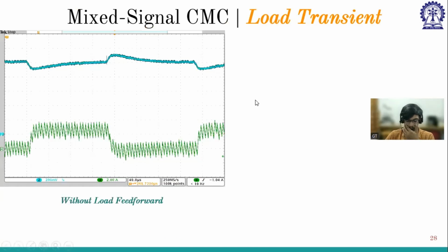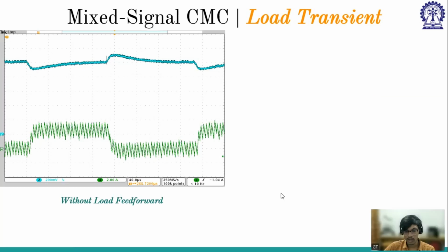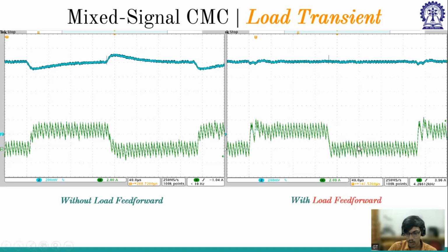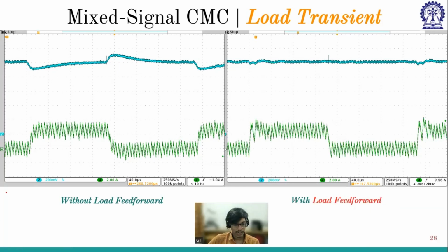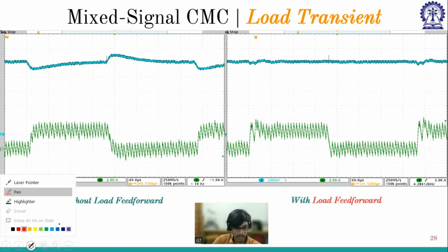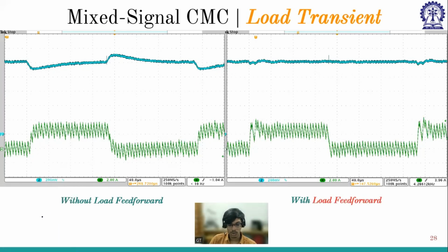Sorry. So now we will go into the comparative case study of load current feed forward and without load current feed forward. Using the design techniques and the Kp, Ki, Kd values that we had discussed how to derive, Sir has done this. In this case, we have Kp, Ki. In the case of this, we have Kp, Ki as well as Kn for that load current feed forward gain.